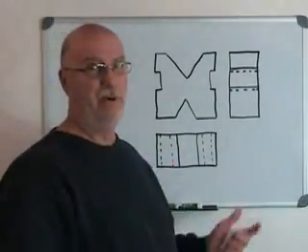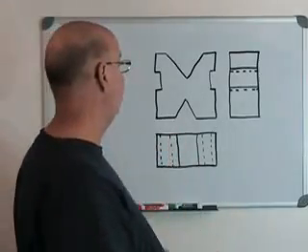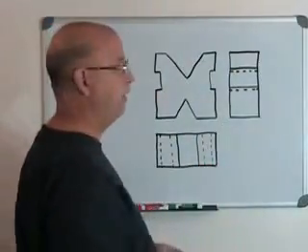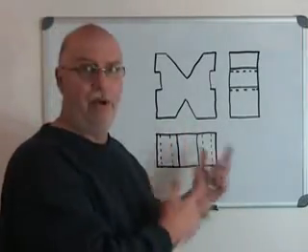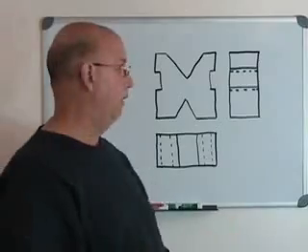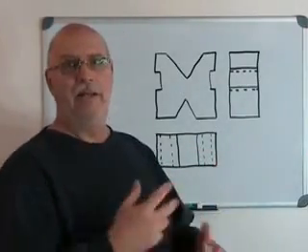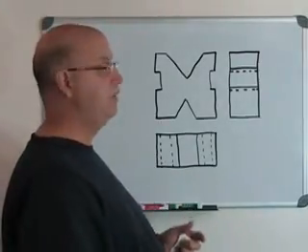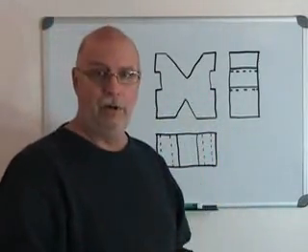It is pretty rough, but it is complete, and all the lines are there, everything lines up, so my projection is correct. Now, if you practice this, if you sketch enough parts, even quickly, you will be able eventually to do it in the reverse order, and that is to look at a projection and imagine the part.